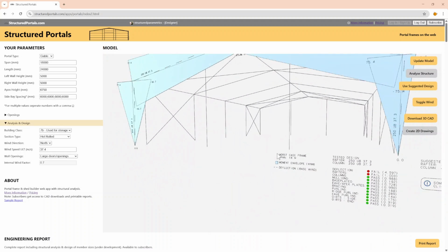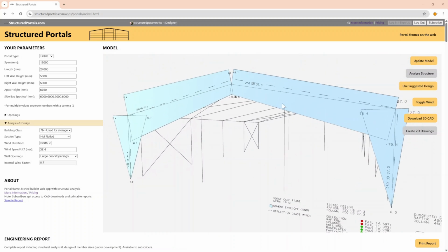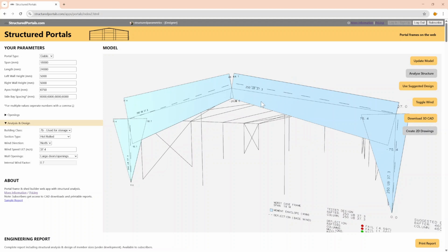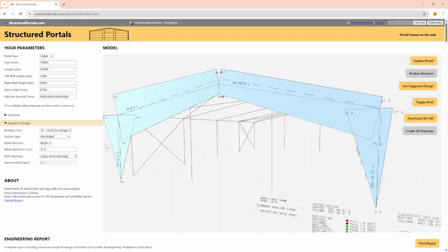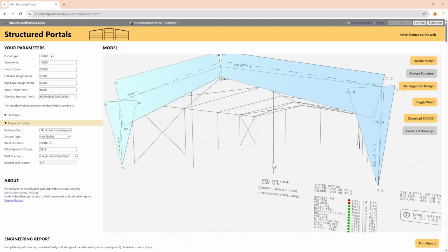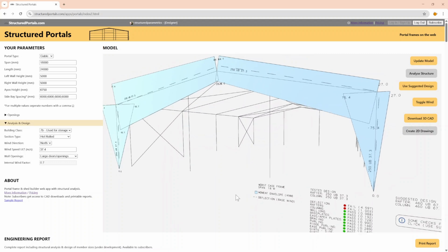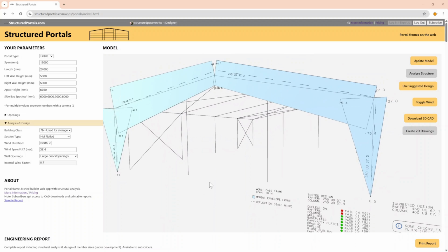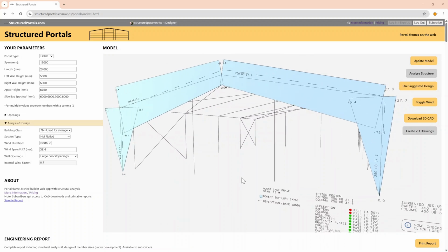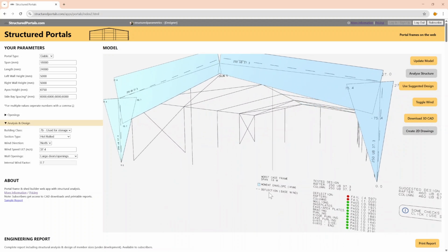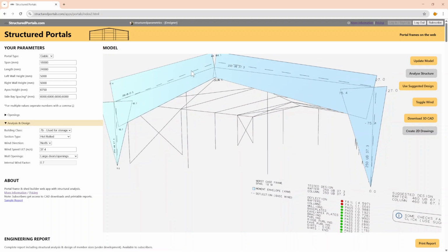you have your worst case frame, which is a moment envelope in blue. So that takes into account all the various wind loads, dead loads, live loads. Cases, it combines them into load combinations, runs all those analysis checks, and comes up with a maximum moment at different points. You can also see a deflection curve dotted in there.